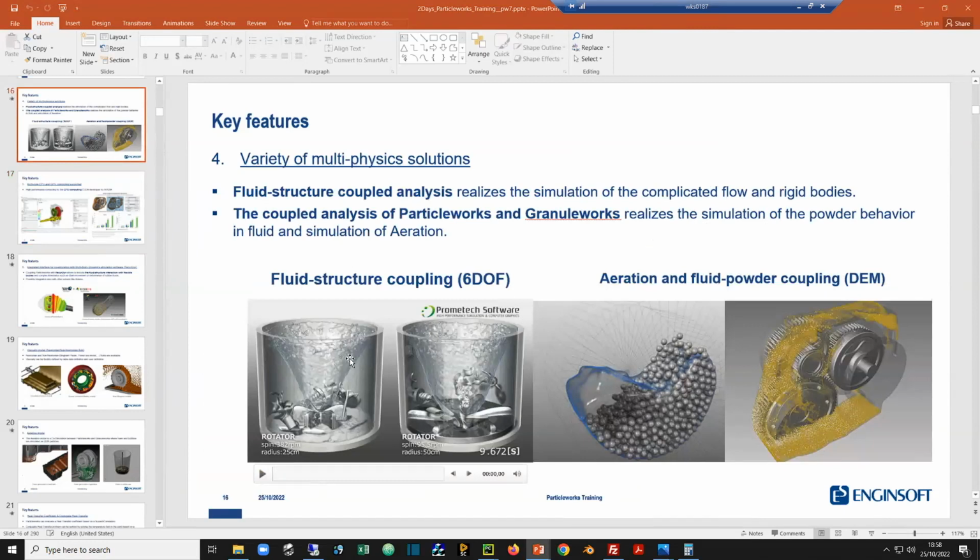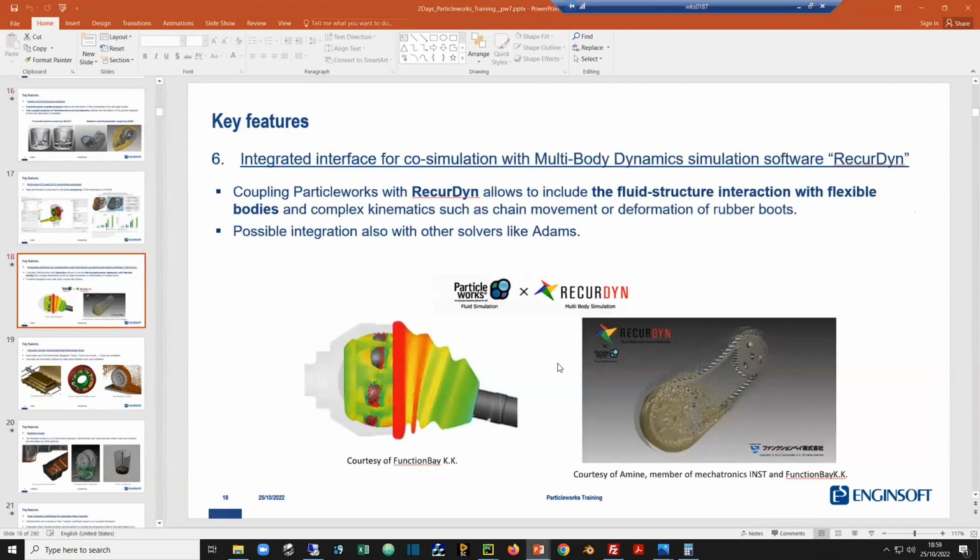Yeah. As I showed you in this slide a little bit fast, we do have two types of boundary condition for solid. One is a boundary condition that we control ourselves, for instance, the rotation or the position, like the external wall and also the fan. But then you see that you have solids floating and moved around by the fluid. Those are discretized with particles inside the software, and they have 6 degrees of freedom. Okay, great. Thanks. And then you have also the capability of coupling with a multibody that has 6 degrees of freedom, but handled outside the software. Okay. Yeah.